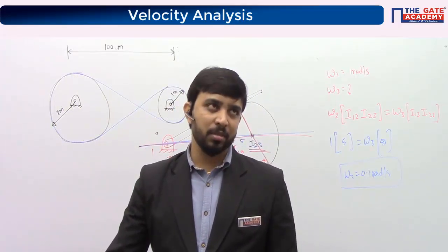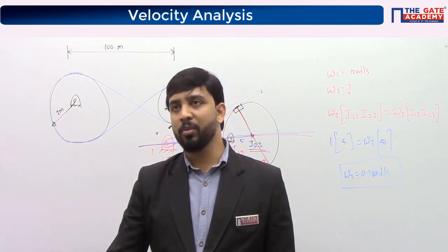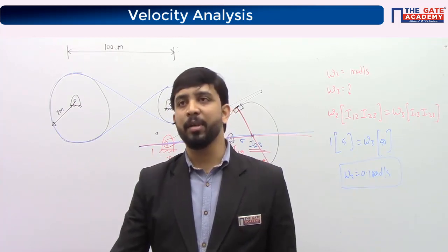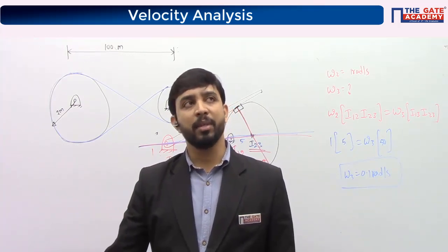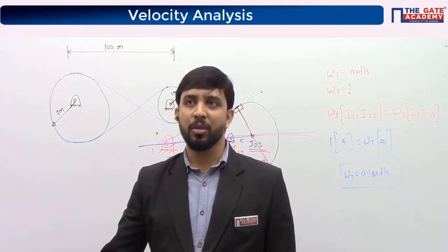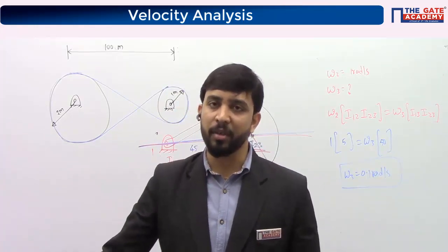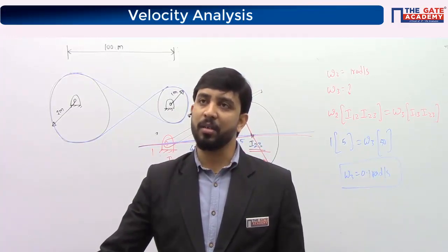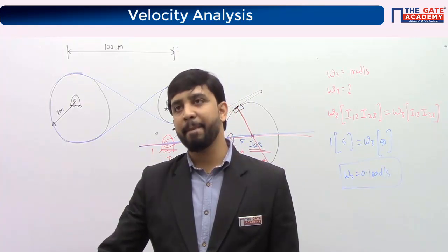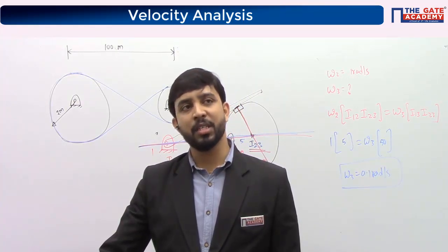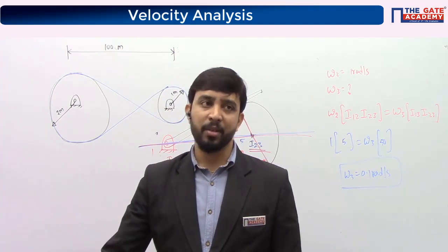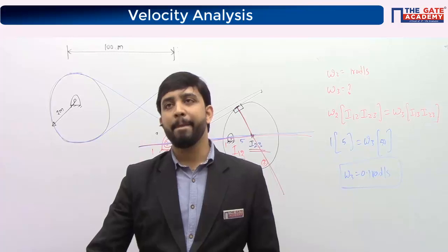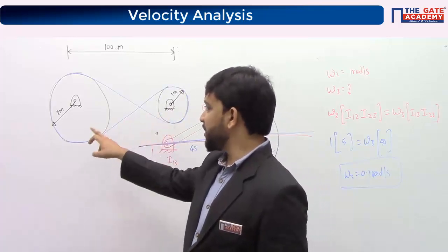So I discussed pure rolling motion, rolling with sliding, rolling with slipping. So what does that mean? And I clearly told you that in a higher pair the contact is only a point of contact, okay. Based on the kind of contact we define that category as higher pair, and there is no restriction on what kind of motion we have. As long as we have point contact, it is a higher pair. Try to look at the common instantaneous center for these two pulleys, okay.